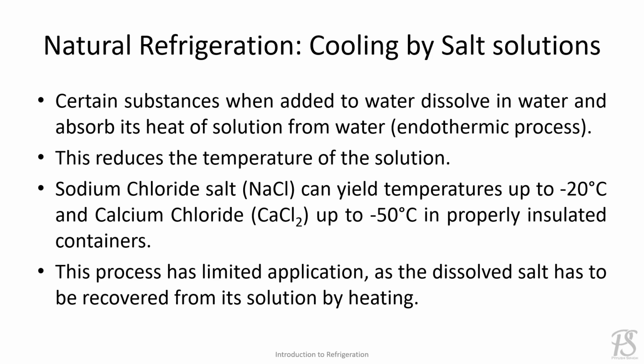Sodium chloride or common salt can yield temperatures up to -20 degrees Celsius, and calcium chloride can reach a temperature of -50 degrees Celsius in properly insulated containers. This process has limited application, as the dissolved salt has to be recovered from its solution by heating.